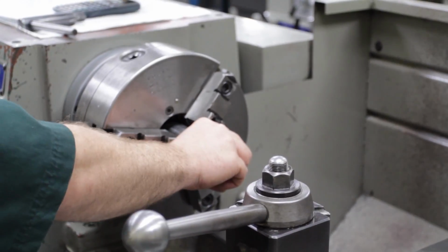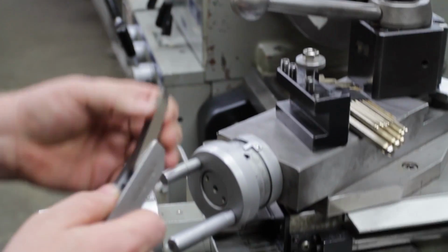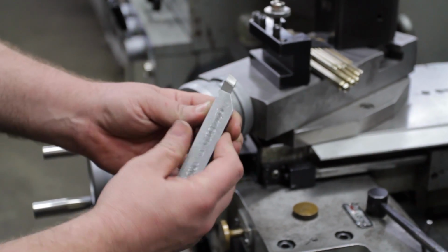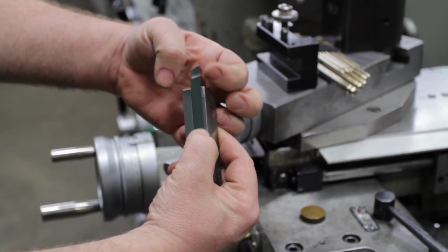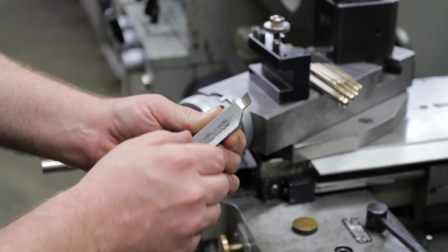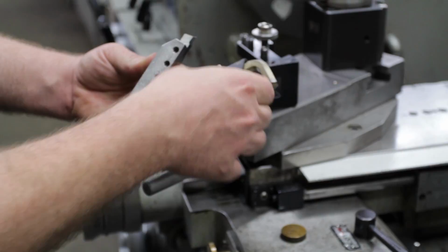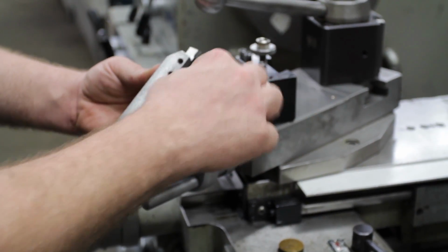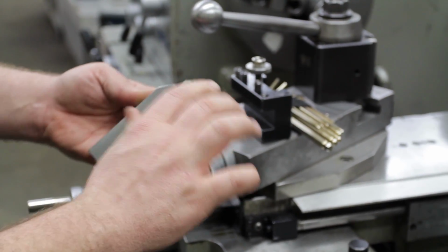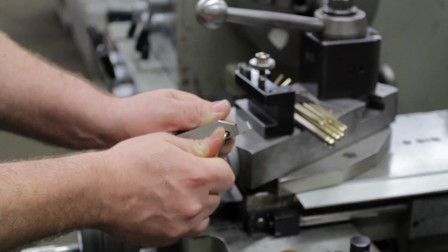After we have our workpiece and our work holding device, we have to set up our cutting tools. Your cutting tool is the one that you ground. The tool holder you made on the milling machine, remember the thicker part of the tool holder is the bottom of it. We'll put the tool in there with the cutting edge on the upper, left-hand side. On the bottom side is where the screws are. You need to find the right Allen wrench. I think it's this one. Yes. When you tighten up these tool bits, you want to work away from that edge. That edge is very sharp, so you want to pull the wrench towards you and away from the tool.